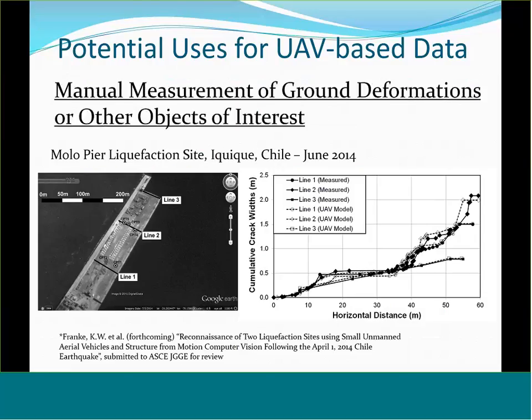Another potential useful application of the data is just to go in and use these models manually. So for instance, if I take that 3D point cloud model of the liquefied pier in Iquique, we can identify transverse lines across the pier, and if we were in the field and we had lots of time, we'd be able to run surveying measurements across and measure the cumulative crack widths of those ground cracks or lateral spread displacements.